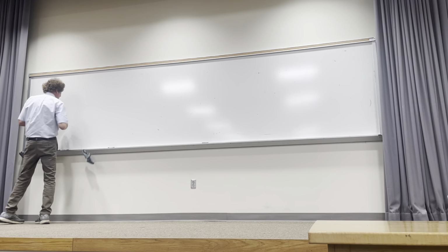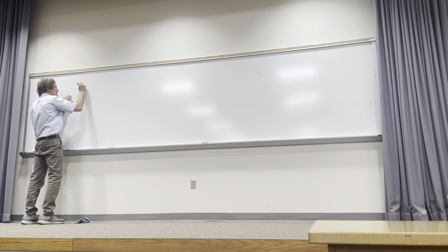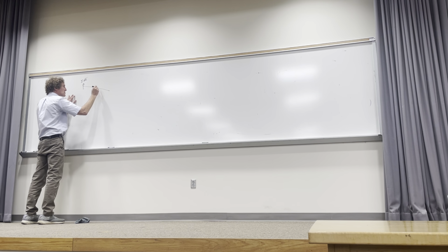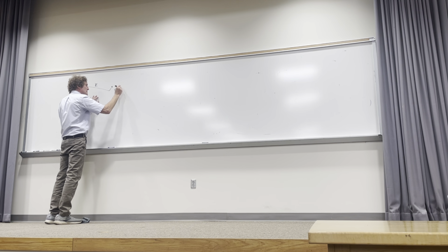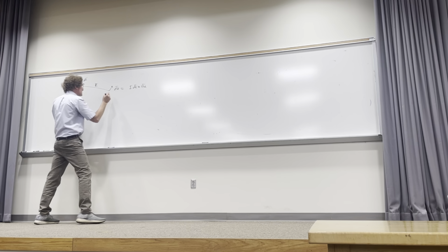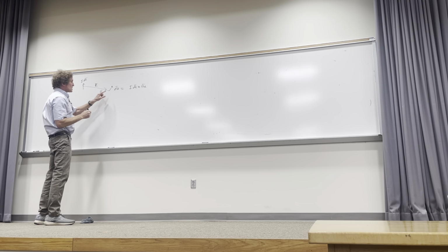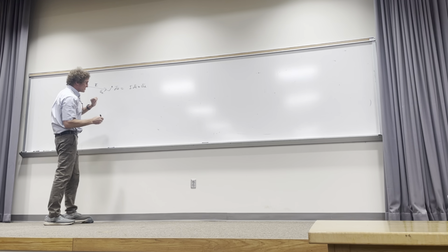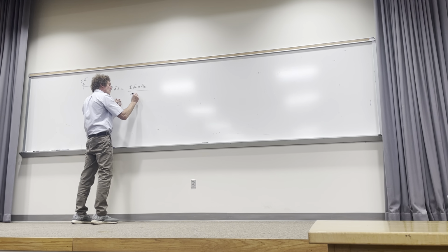All right, so next thing is this. We know when we have an actual current I dl, and that's a vector, and you have a radius vector r, and you want the dH from this, that's equal to I dl crossed into a_r, a unit vector pointing from the current source to the position you're observing the H field, over 4 pi r squared.